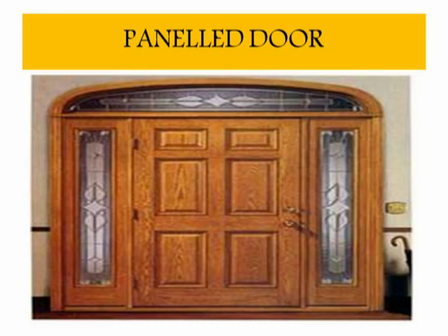Here is a picture of a panelled door. You see that there are a total of 6 panels. Two big panels are there, and on the top there is a relatively smaller panel. The horizontal members connecting the different panels are known as rails, and the vertical members of the shutter are known as stiles. Here the ventilation is also visible, so ventilation is also constructed with the door.